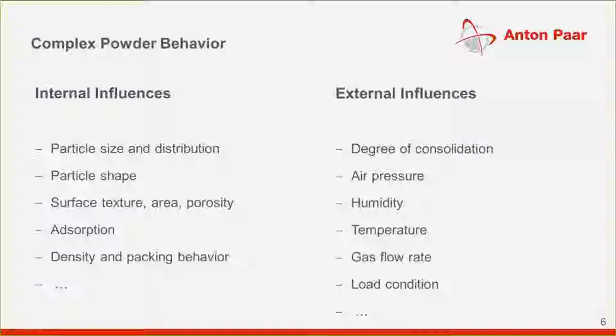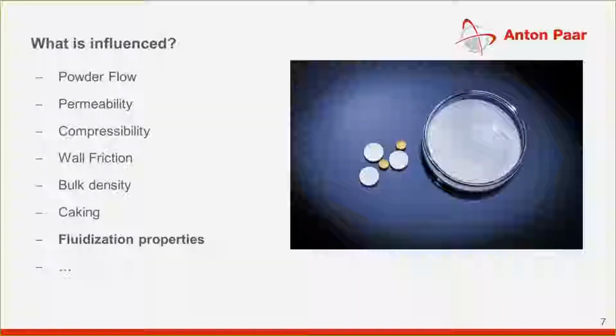If we look more towards external influences, there are quite a lot as well, but specifically towards fluidization, we might want to have a look at humidity, gas flow rates, and of course also whether the powders were pre-consolidated. These internal and external influences change the powder behavior. So they will impact, for example, how the powders flow and how they can be compressed. But in this webinar, we will focus on the fluidization properties and how to measure them.